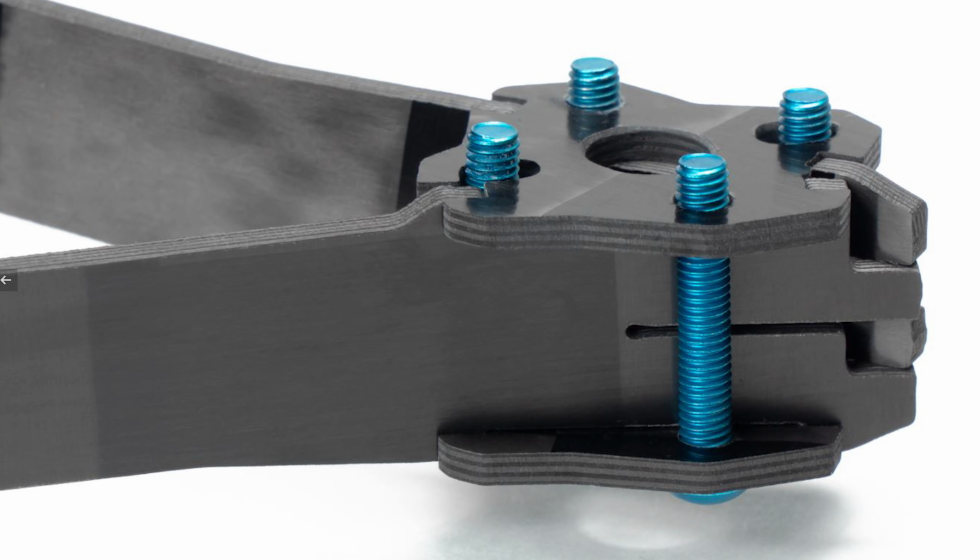The downside with this technology is that it's a super expensive machine. So every hour it's costing a fortune. And every start hole is a problem because if you try to punch through, it will delaminate like crazy. So if you try to make a small hole, you need to drill a hole first, and then start cutting in this hole to not get this delamination.